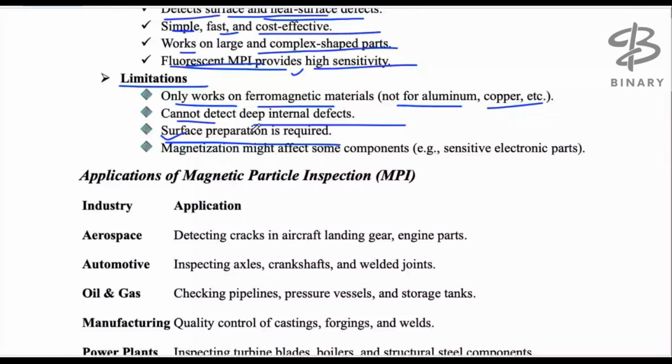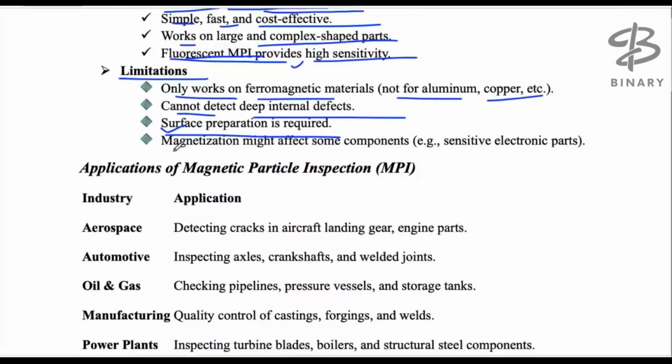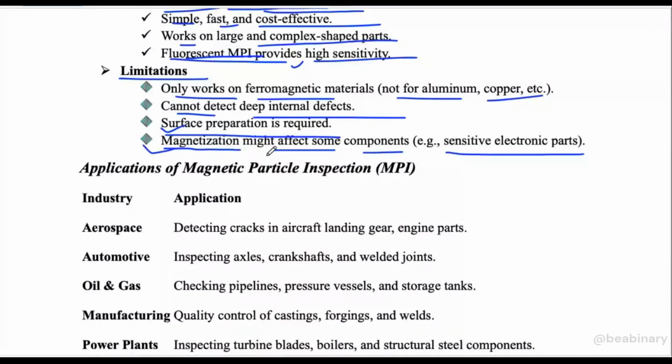Okay, magnetization might affect some components, for example sensitive electronic parts. So this is the bad thing, because due to the magnetization some parts may get affected, and for that we must take care. If such parts are there, then we cannot use this technique.